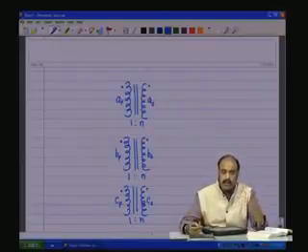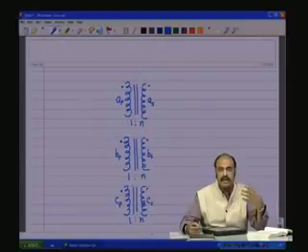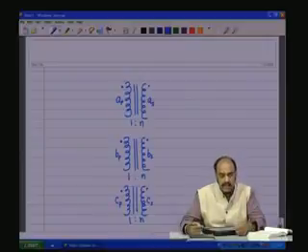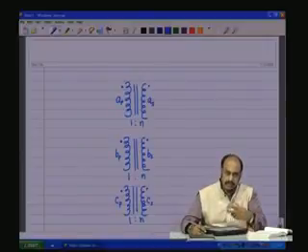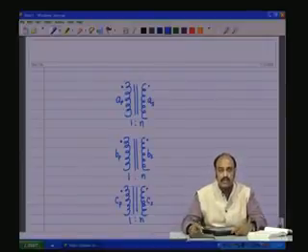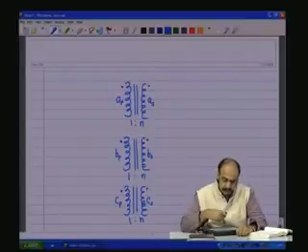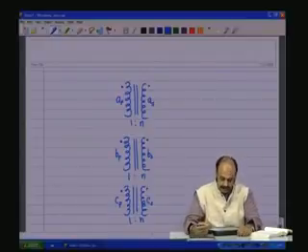Now, the three primary windings can be connected in one of the topologies, star or delta, and the three secondary windings can also be connected in one of the topologies, star or delta, which will result in four topologies for the entire transformer.